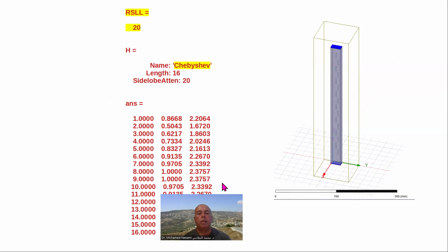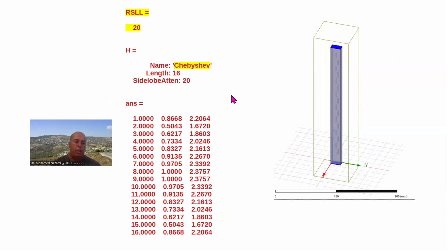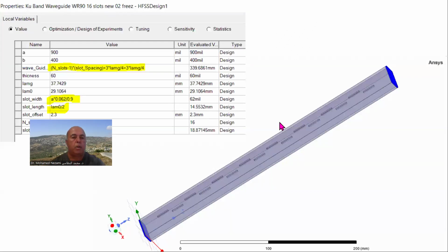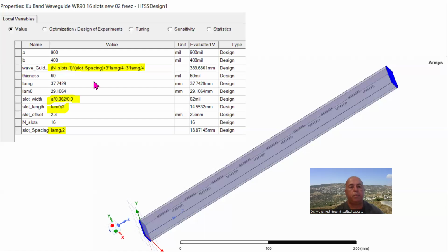And then, of course, in a lot of cases you don't need 40 dB of side lobe. That's too much, because the trade-off is that it really widens the main beam. I said, no, I want the ratio of the side lobe level to be 20 dB in this case. And you get this here. This is basically your window, and these are my distances. All right, so we have this design in here.